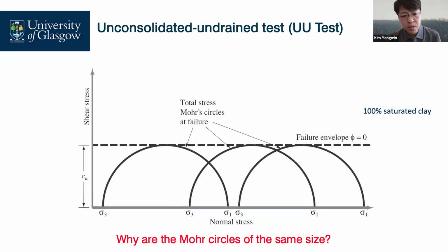Why? For example, your friend's group starts at 100. Off the top of my head, high confining pressure means these soils withstand high deviator stress, so my expectation is a larger Mohr circle, but still the same diameter as yours.